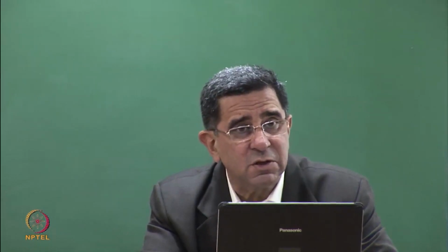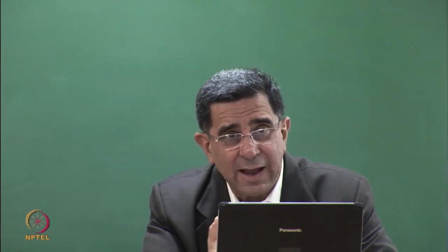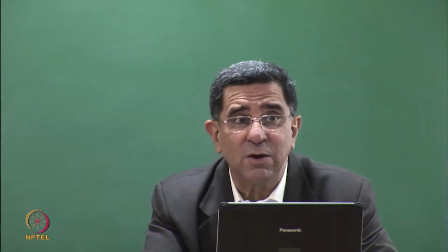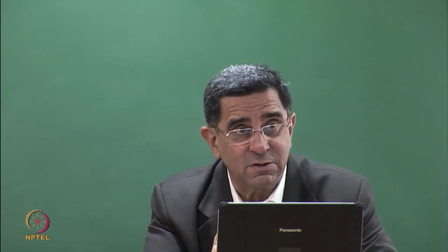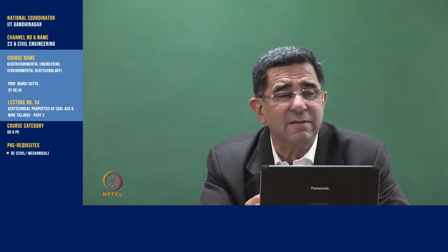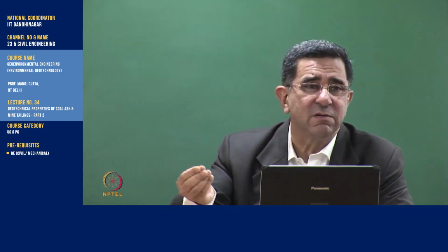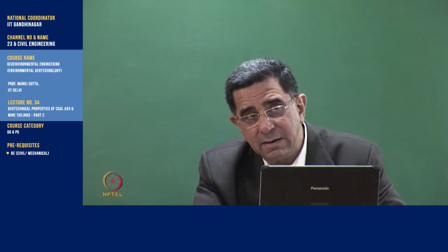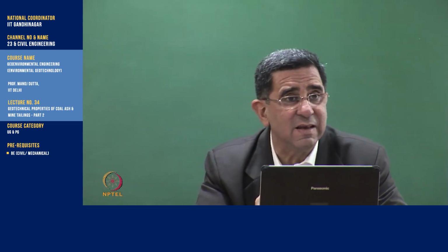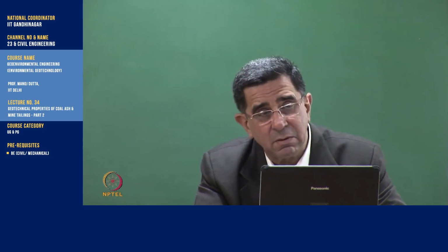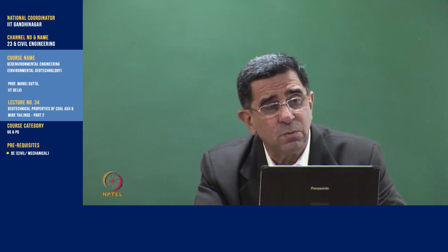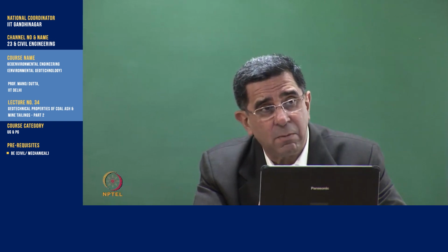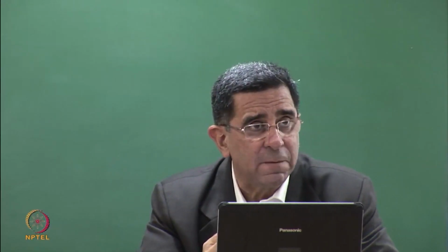I showed you in the composition there is some CaO, right? And I showed you that there is some SiO2, and this SiO2, I told you, is amorphous, that means it is reactive, it's not crystalline. So CaO will not react with sand. Suppose I take SiO2 in the form of quartz grains, and if I put lime on top of it, they are not going to react. But if I have reactive silica and lime, I will get a CSH gel, but a nominal amount. So ash does show self-hardening properties, which is of interest to structural engineers.